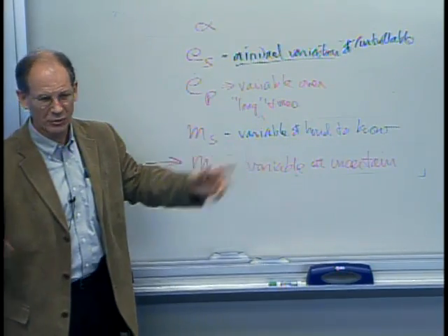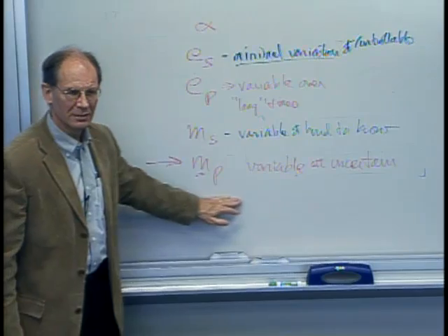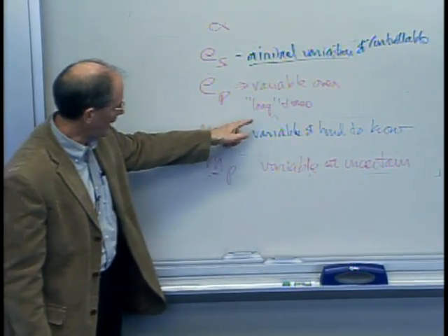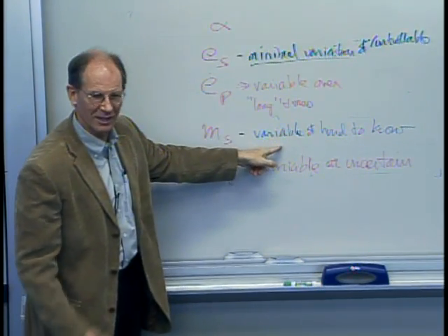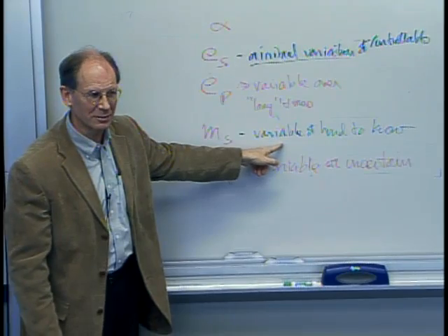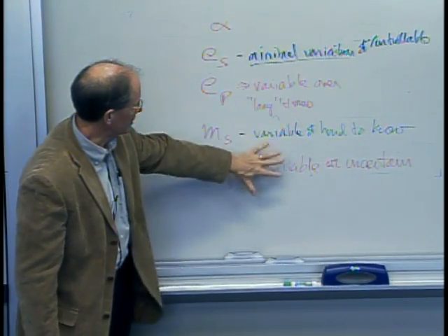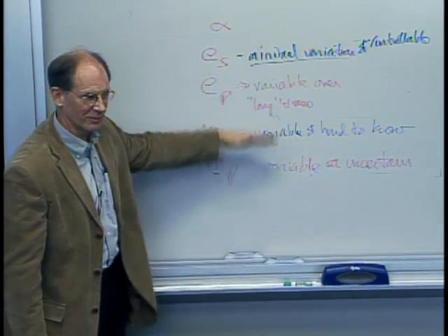So here's the moral of the story. The biggest source of variation tends to be material uncertainties, just inherent in the material, and, if you will, the coupling between this energy source and how well it actually gets into the material through sort of an uncertain interface. So all of these things here, these three, are your sources of variation typically in differing measures.